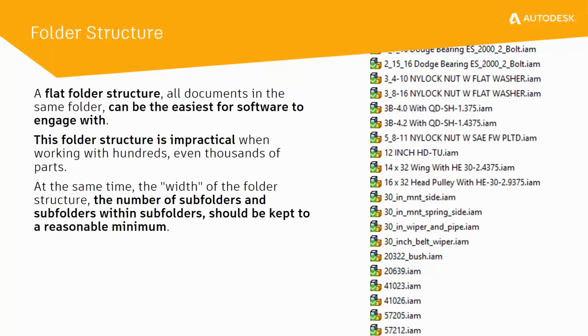Also, top-level assemblies should appear in the same folder where the project file is located. And then put all of your parts and sub-assemblies inside of subfolders inside of those directories.